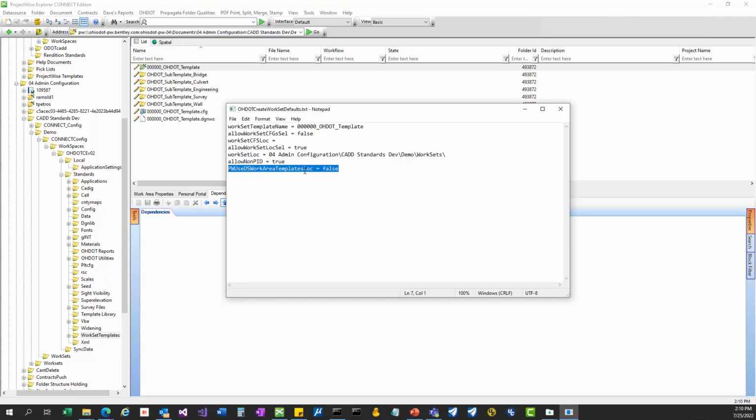The sync tool for V2 does not put this template there for you automatically. Our V1 sync tool did, but our V2 does not do that anymore because a lot of people didn't like it. So I just said, fine, I won't put it there. I'll just use this default location. If you want to use your work area templates location, then just set this to true, and all you have to do is copy the template over to wherever you define that location, and then it can be with the rest of your templates that you might have for that data source.